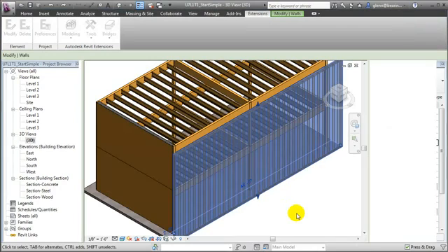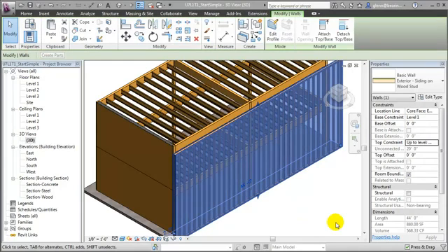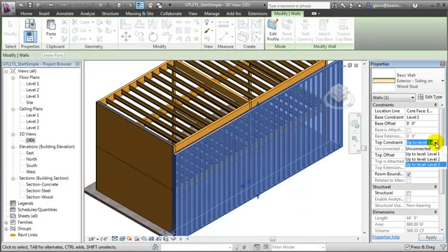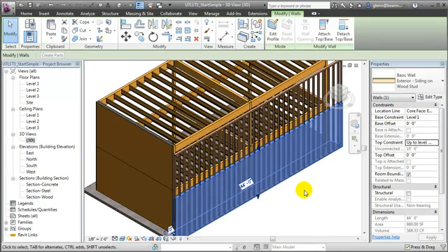And when we return to the Revit window, you can see that we've added studs to those walls. They're currently spanning 2 floors, so we'll want to make some adjustments to that wall, as well as adding a few openings to it. Let's change that wall height so it only spans a single floor. We'll change the top constraint to level 2, say apply, and the wall moves down. The framing elements haven't changed yet. We'll need to rerun the extension to have them update.